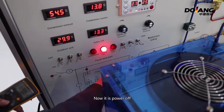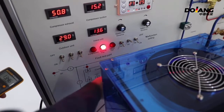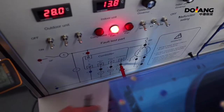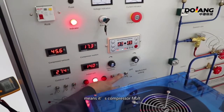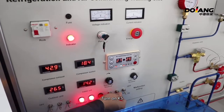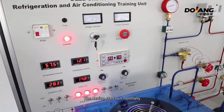Now it's power off. Use a multimeter to measure it. It means it's a compressor fault. Turn on K5. Press the on button of the remote controller. The evaporator indicator lights on, and the device runs normally.